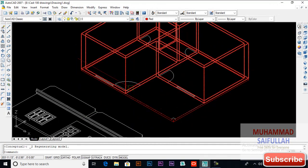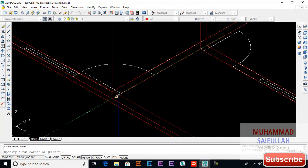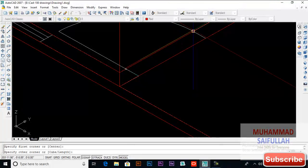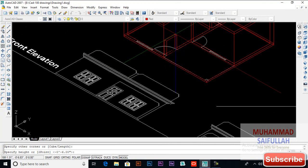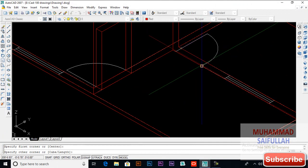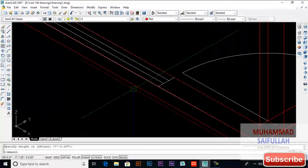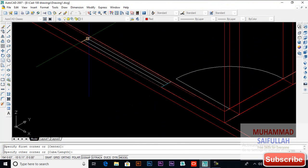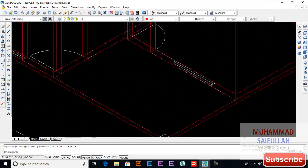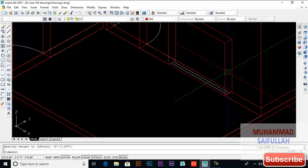Now I will draw doors and windows, a box here, select this corner and select the outside opposite corner and give it a height of 7 feet. Again draw a box from this corner to this corner and give it a height of 7 feet. Here I will draw a box again and I will give it a height of 5 feet. Again a box from here to this point and 5 feet.